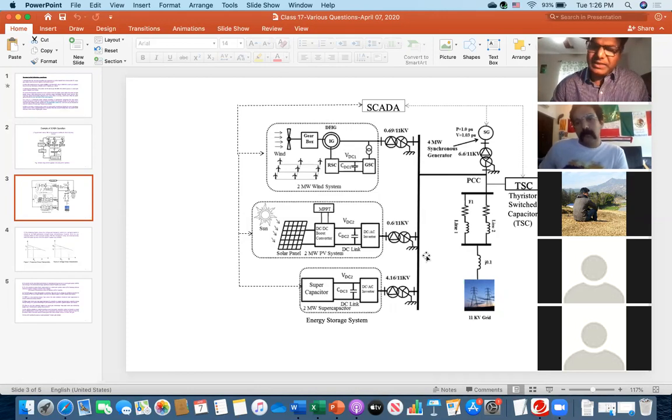I mean, you can use current. There is no issue technically, but you have to measure the current from the various sources, and current is not a common variable. Again, there might be loads in the system that draw different current. That's why it is appropriate to use a global variable, in this case, the voltage information. What voltage is available here? A common voltage.